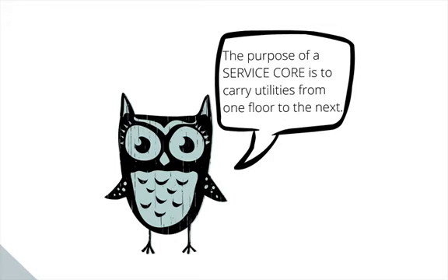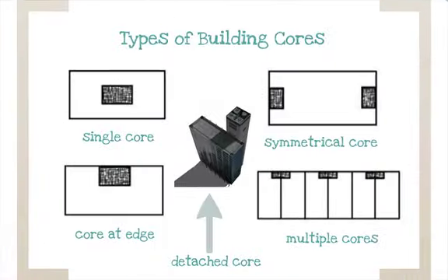It's a lot less expensive to put bathrooms on top of one another so they can share all of the pipes and the vents than it is to place them sporadically throughout a building. The location of the core is very important to the design of the building and you as a designer. You must be conscious of the location of the service core to rentable spaces in the building because it has a direct impact on the safety and the comfort of the occupants.